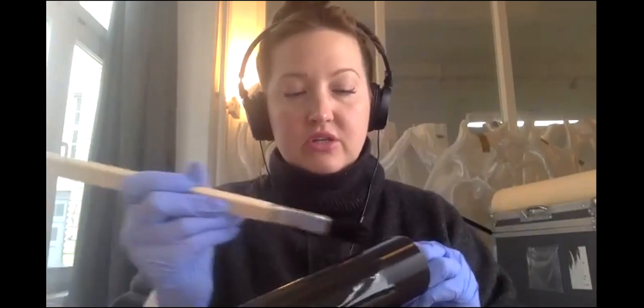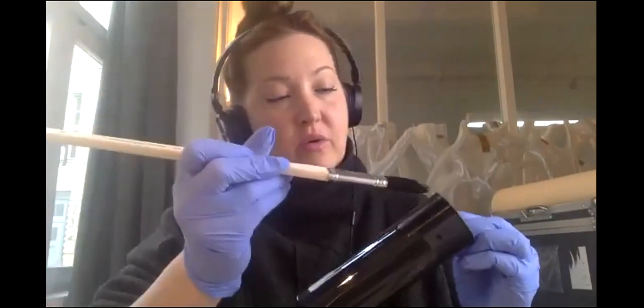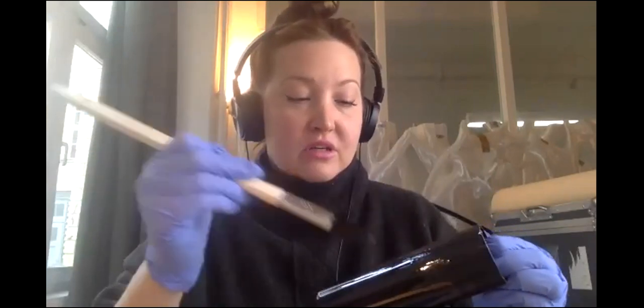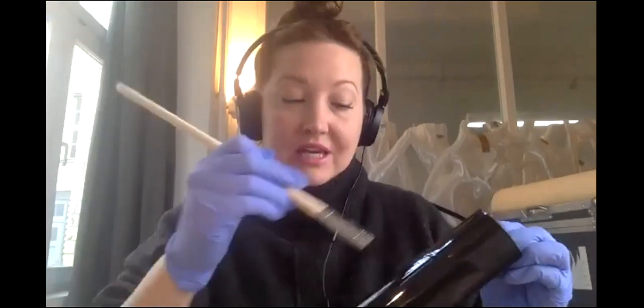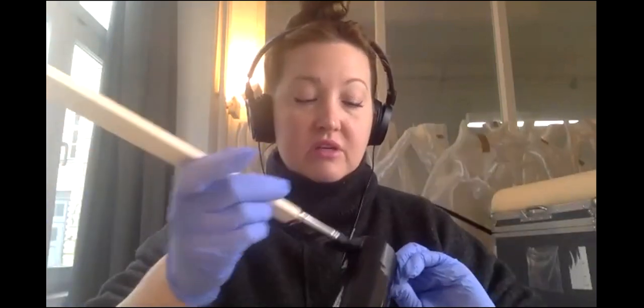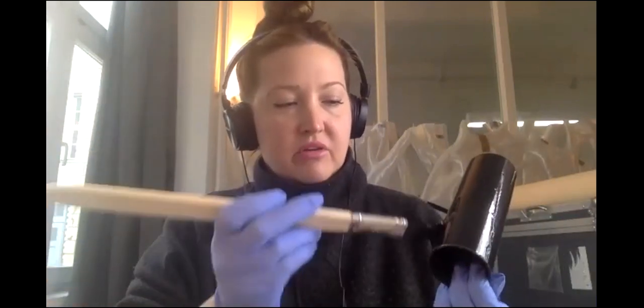What is your best recommendation for smoothing PLA? I would really suggest what I'm doing here. If it's really just a smooth surface, this is the easiest thing. As long as you can reach the area with the brush, it works really well. And you can also sand it afterwards, paint it afterwards, anything, and you're also strengthening the part in addition to that. So I'm a big fan of what I'm doing right here, and it's specifically formulated for 3D prints. It works on PLA. It works on pretty much any material that BigRep sells.